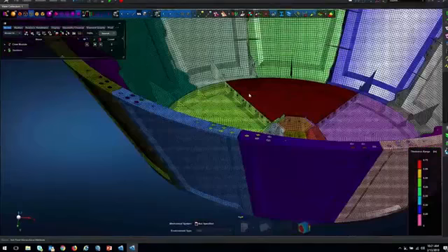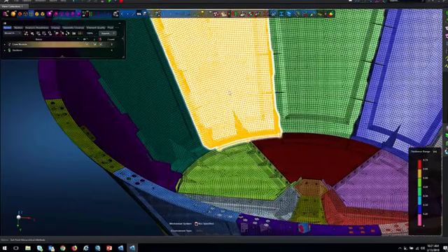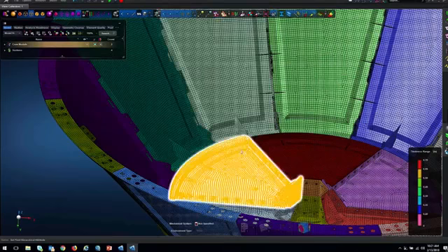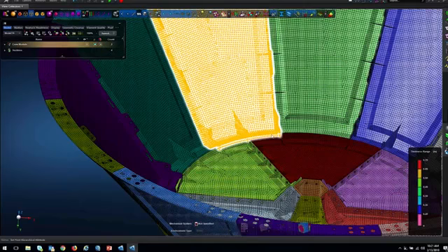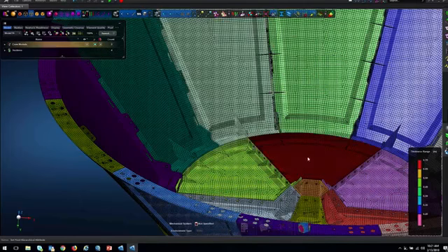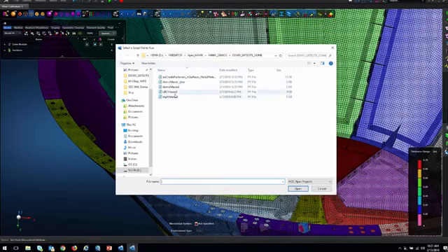So in this model, for example, between this side panel and these 2 flat panels is the area where it is welded. And we are going to use the glue technology to connect those parts. And I'm going to run the macro to create the glue between those parts.